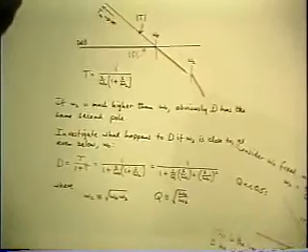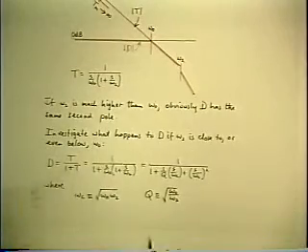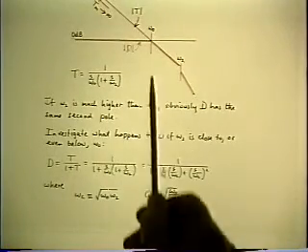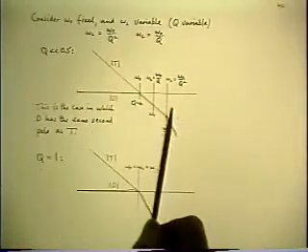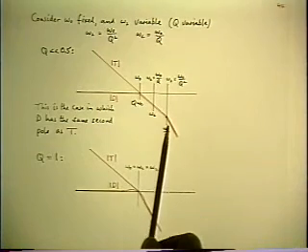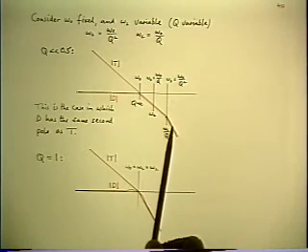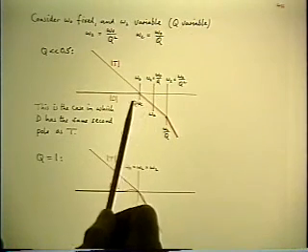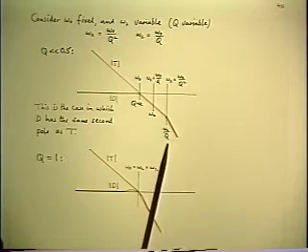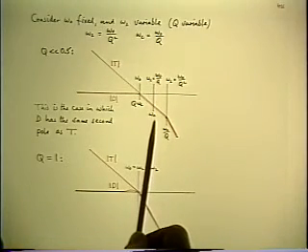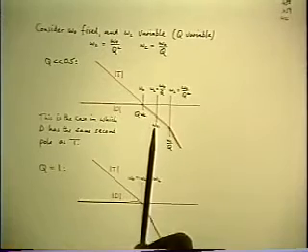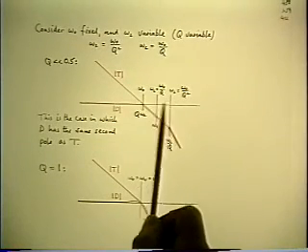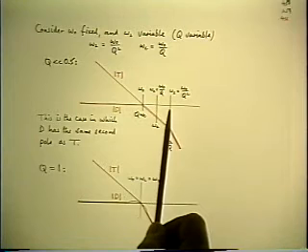Because if Q is much less than 0.5, you can factor the quadratic into the two approximate real roots, of which the first one is the first two terms, which is the omega 0 pole, and the second one turns out to be the second pole in T. So as we already expected, the shape of D has two real roots at Q omega c and omega c over Q relative to the corner frequency, and the corner frequency is the geometric mean between omega 0 and omega 2 by its definition.